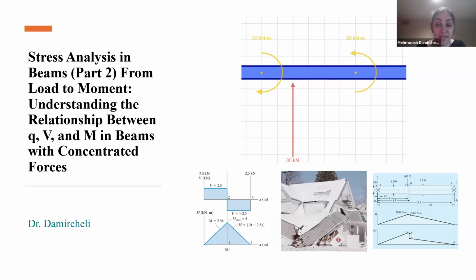By the end of this lesson, you will know how to draw shear force and bending moment diagrams for a beam with concentrated loads and moments, identify jumps in shear diagrams and slope changes in moment diagrams, and jumps in moment diagrams that are related to load, shear, and moment through differentiation and integration, or area under the curve.